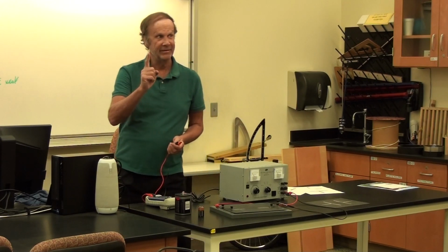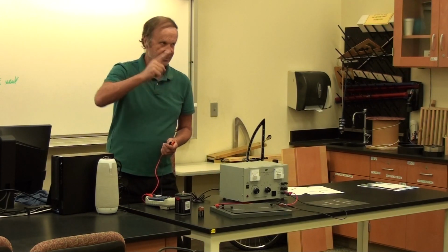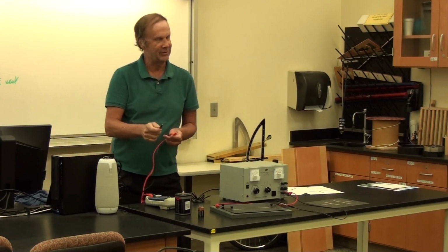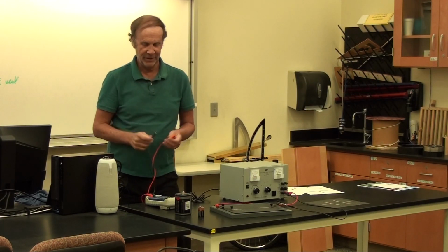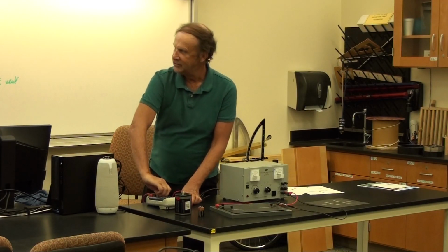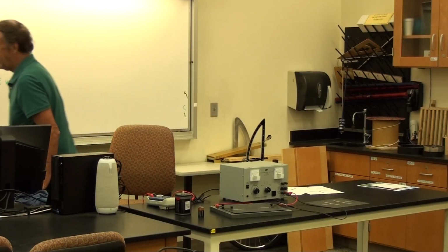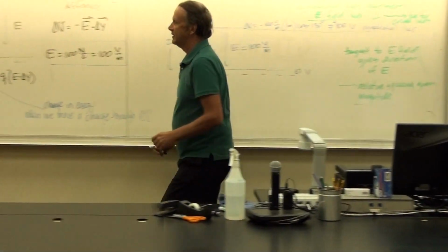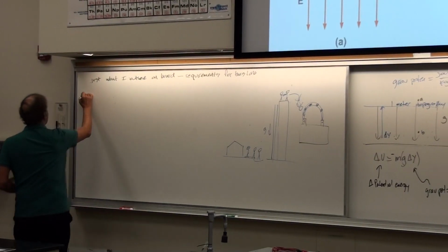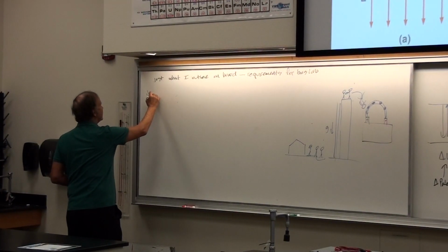But with an analog meter, not idiot-proof, that'll try to drive the needle in the wrong direction if you don't hook positive to positive and negative to negative. But with a digital meter, you don't really have to worry. So measure those two voltages. So that's step one. Pretty simple, but it just gets you used to the concept of measuring voltage.